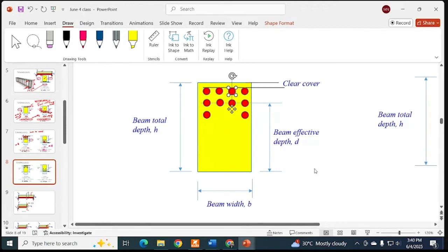Here, it is suggested that you do not have to accurately calculate the centroid. You will consider that all the layers have equal number of bars. So the center will be considered to be located here.